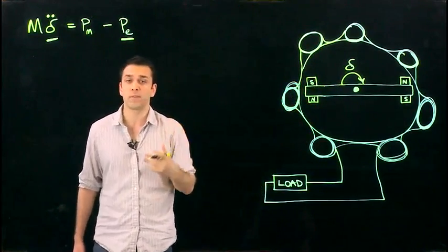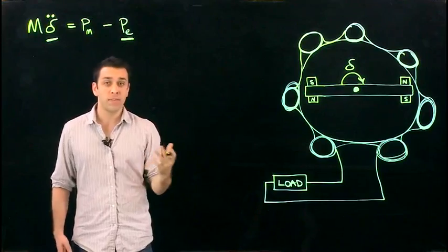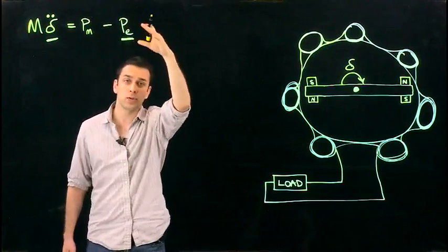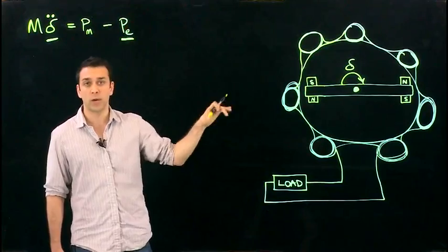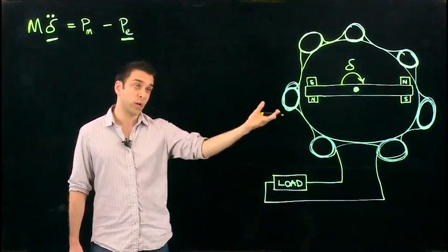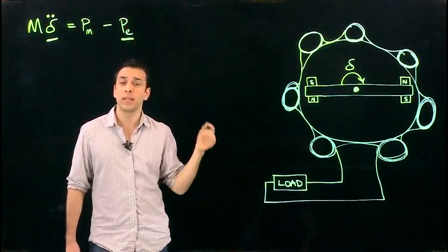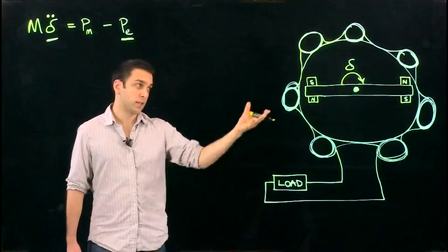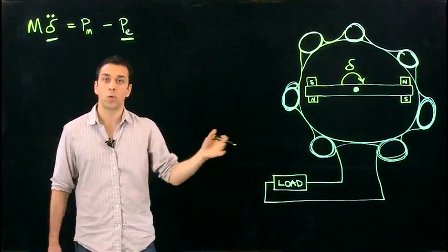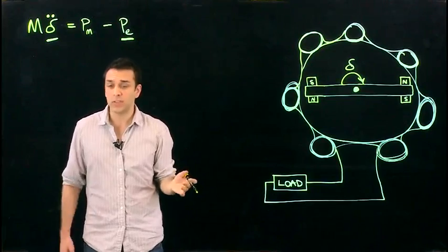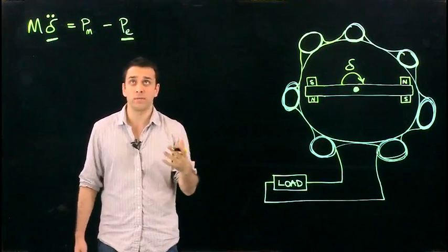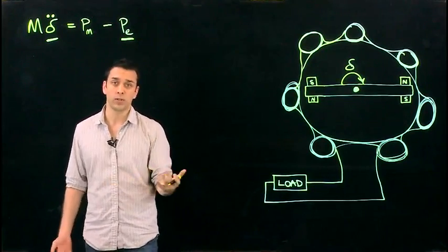So engineers might have to shut down the generator. If this happens, this term, the electrical loads in the system, might change, spike, or drop. And well, when you shut it down, they'll jump up suddenly. And all the remaining generators might get stressed and have to be shut down one at a time. And so if this happens, you might get cascading blackouts. You can have different effects that we want to model and understand.